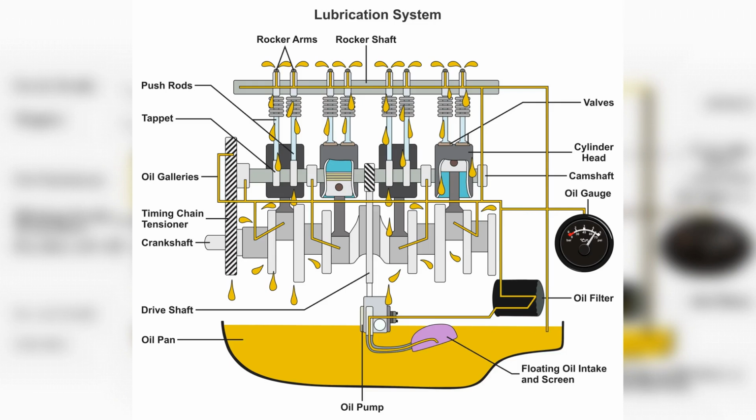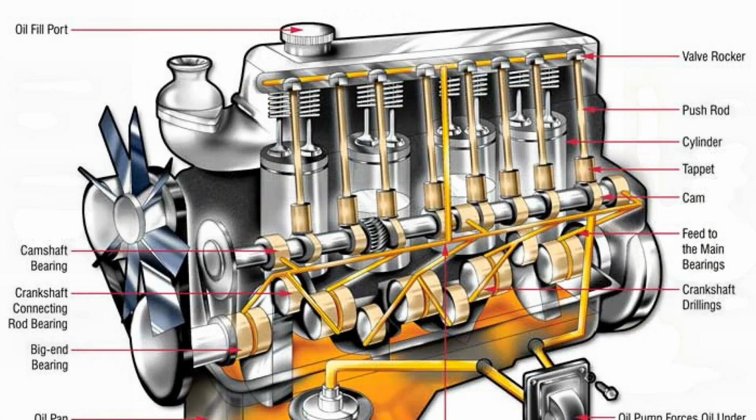It should be noted that depending on the design features of a particular engine, the pressure created by the oil pump in the oil line can be in the range of 2 to 16 atmospheres. The oil radiator is the next element of the lubrication system. Its main purpose is to cool the working fluid, since it does not reduce the temperature sufficiently in the crankcase sump. There are two types of radiators, airflow and liquid-cooled.